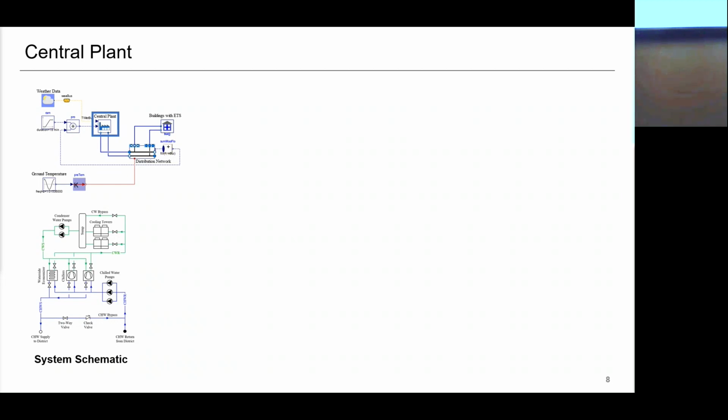For some of the fifth generation combined district heating and cooling systems, that's still a bit of an unsolved problem how to do it best, because they typically have pipes that are non-insulated, and you actually want to exploit the heat transfer with the soil. So I think a good approach there, so far, is to use radial heat conduction to the soil, but it's a bit of an open question how far you want to go there, because the heat conduction is not purely radial, since at some point you start exchanging heat with the surface.